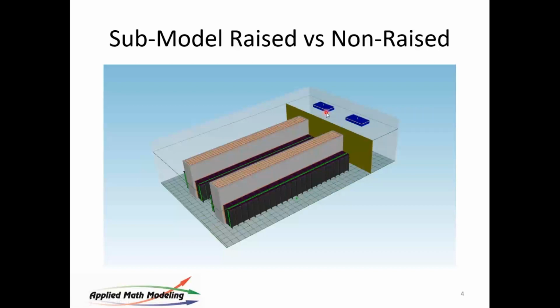So the way this room works, again, is you have two air handlers here dumping air down into the room, coming down, turning this corner, and flooding this room with cold air. They often call this a flooded room design.